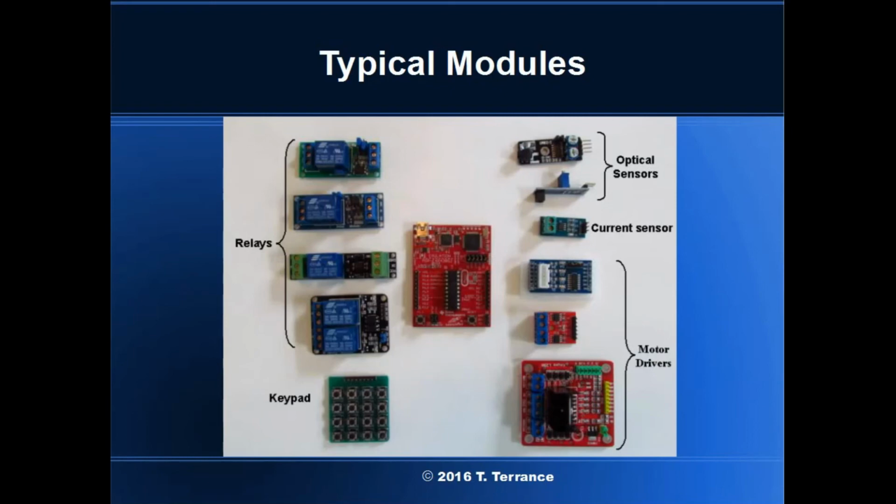These modules operate at various voltages and current levels. This will all work if there is a common ground between them. Tie all of the grounds together, including your microcontroller, with at least one wire. The electrons know where they started and where they are going and will sort themselves out.